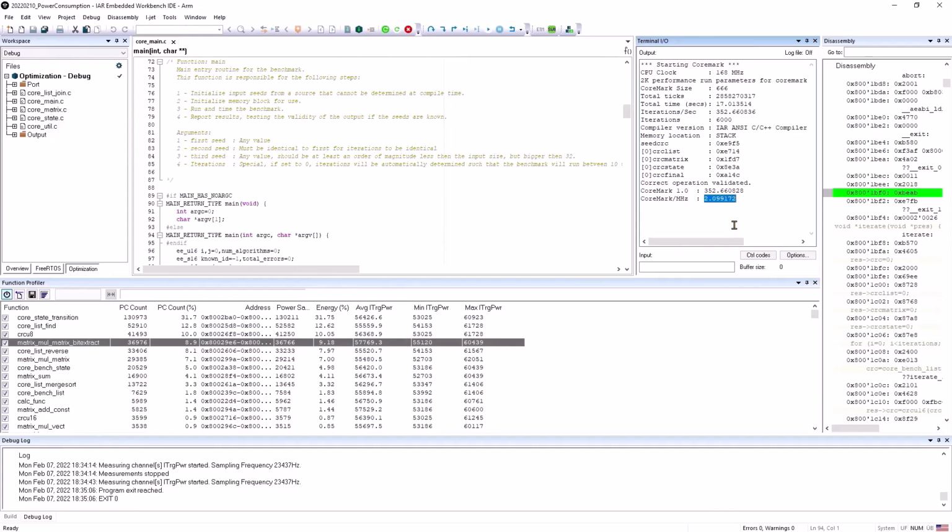So if I want to reduce the power consumption of the application, I would have two options: increase the performance and then put the controller for some time into sleep mode, or increase the performance and reduce the clock frequency of the MCU. So if I need to increase the performance, it's a good approach to start with the function that is executed most of the time.